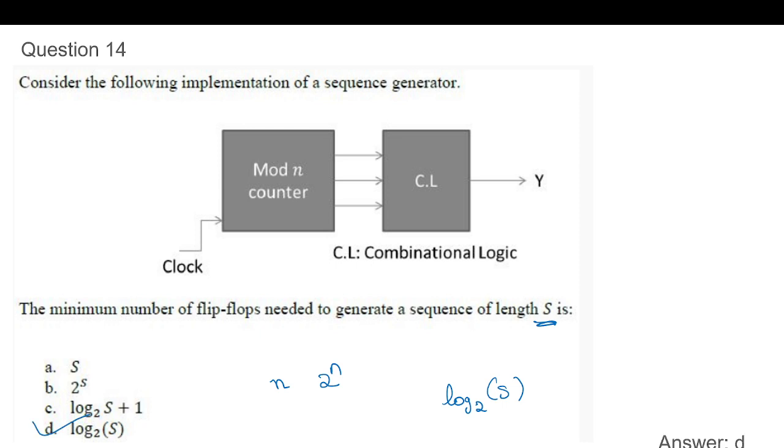Ma'am, can you repeat once again? Yes. If we have n number of flip-flops, then 2 to the power n will be the length of the sequence, right? Now they have given this, if we take log 2, the S will be the n number of flip-flops. Okay, ma'am.